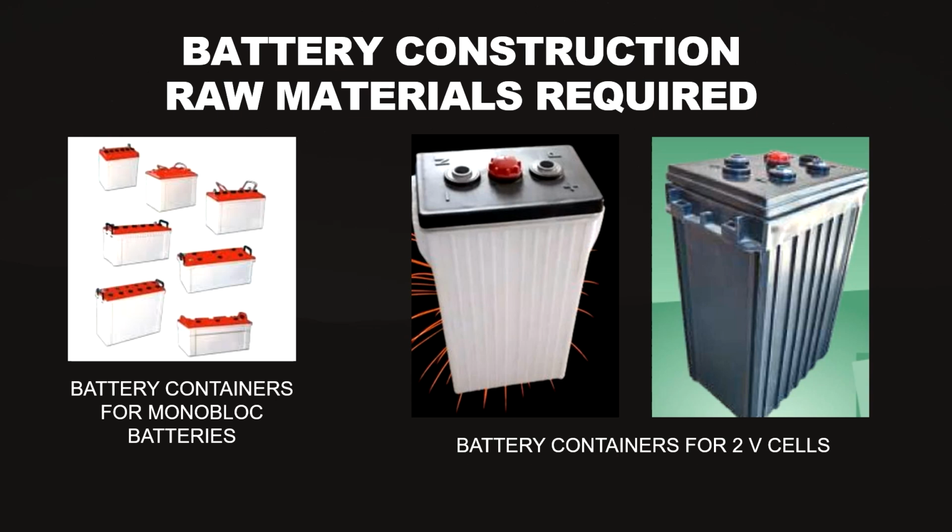batteries, and similar containers are used for traction batteries too. When it comes to industrial golf carts, scrubbers or sweepers, monoblock containers are used, similar to the ones used in the automotive industry. However, these industrial batteries are typically made in a 6 volt and 8 volt configuration. When they are sometimes made in a 12 volt configuration also, the containers may not match the size of the automobile containers. So those containers are a bit different.